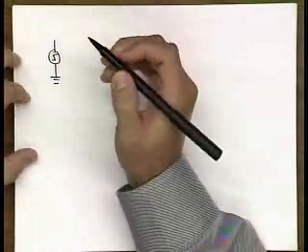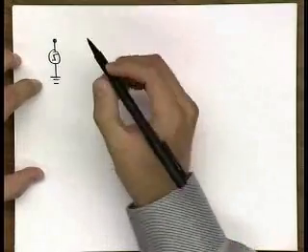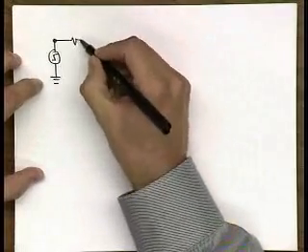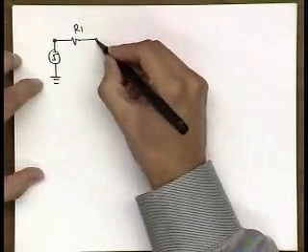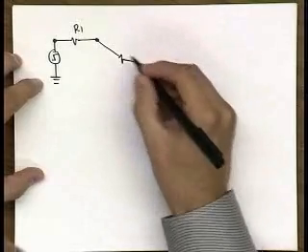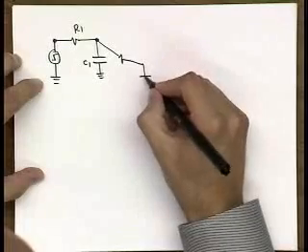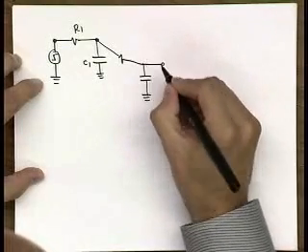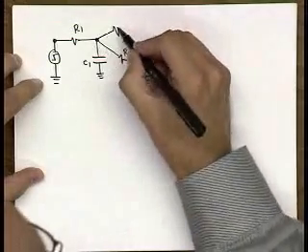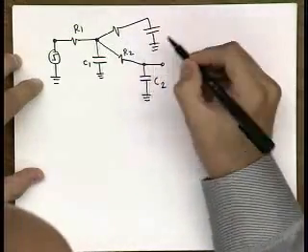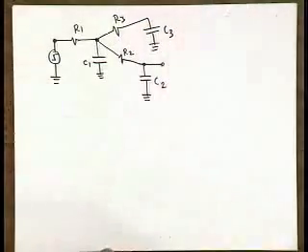So as always, we analyze the propagation delay assuming step input. That's really important to understand. It's also going to be useful for your midterm. So you have a simple network like this: resistance R1, then we have capacitance C1, then we have another branch R2, and then we have C2, R3, and we have C3.